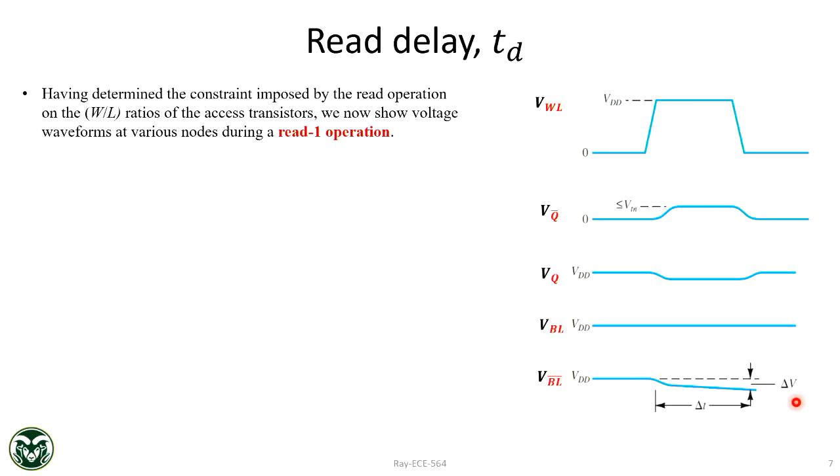For example, at the beginning, when 1970s SRAM was first proposed, that time the sense amplifier was not there. And you can see the timing will be in maybe micro or milliseconds, right? So later the sense amplifier was invented because of this need that I want to sense faster, readout should be fast. So that's why it will speed up the read process.